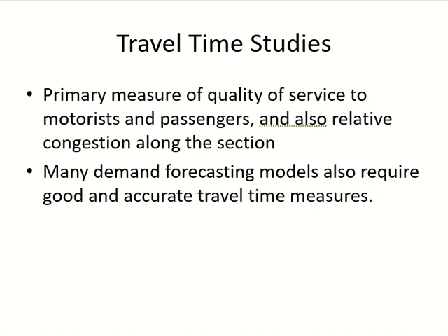If you've taken a longer distance, your time will be maybe more than 10-20 seconds. The value of 10-20 seconds is more stable. The value within 1 or 2 seconds is like a fraction, it's passing like this. So times taken for very small distances are not considered valid for travel time studies, because in this much distance, your travel time is not stable.